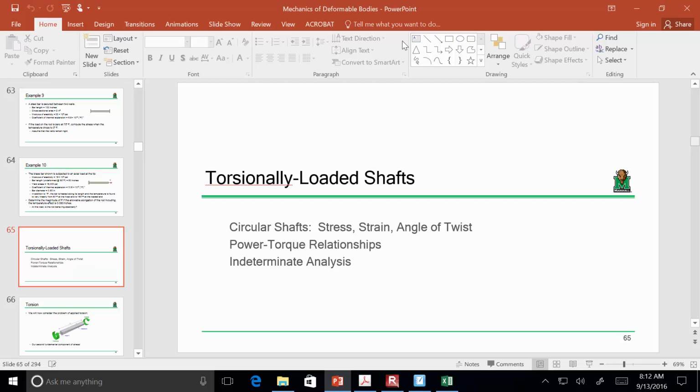So problem 2, 4, 5, just so everybody's clear, is the second problem on the homework assignment, and it's the problem that involves the weight attached to 3 cables. And what I will say is this. This problem is essentially the same thing as that composite column, because you've got an axial load supported by a column. In this case, it's a cable, but it's the same deal, supported by a column of 2 materials.